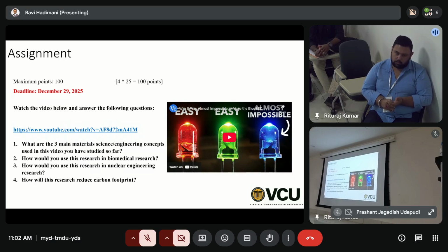The second one is you want to have not a jagged surface. You want to have a smooth surface of monoatomic layer, which means we are talking in terms of a few nanometer roughness, which silicon wafers are like. Our glass might have 10 nanometer surface roughness.